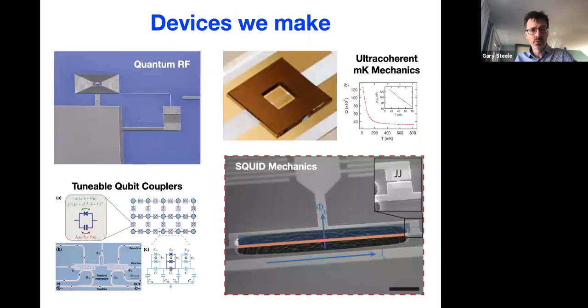That's a little bit of a feeling for what it looks like in the lab. Part of our work is building these setups in the lab. The other part is building the devices we put into this fridge to measure. These consist of little wires of superconductor, which we sometimes wind up into an inductor. Sometimes we make them into a giant capacitor, and sometimes we actually do something else, which is make a device I'll tell you more about called a Josephson junction. And we have a bunch of different directions. We have two main directions, one where we look at the circuits on their own and applications of the circuits, and the other where we use these circuits to try to detect mechanical vibrations.